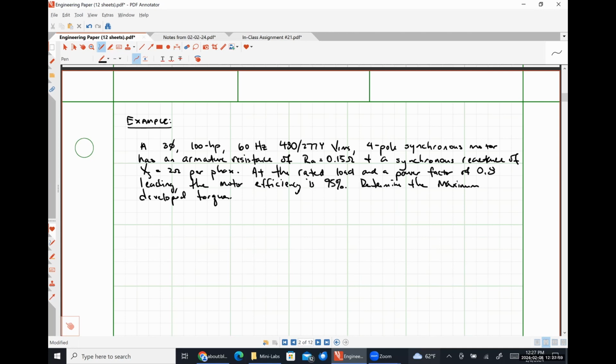In some specific instances, industrial sites will actually run an unloaded synchronous machine as a power factor correction device instead of utilizing a capacitor bank, like what's been discussed in your previous power classes on grid scale solutions, right? So you can use a combination of synchronous machines and induction machines in order to not have to employ standard power factor correction techniques. And it's all because the synchronous machines can actually be operated at a leading power factor, unlike an induction machine. That's pretty darn interesting, at least to me.